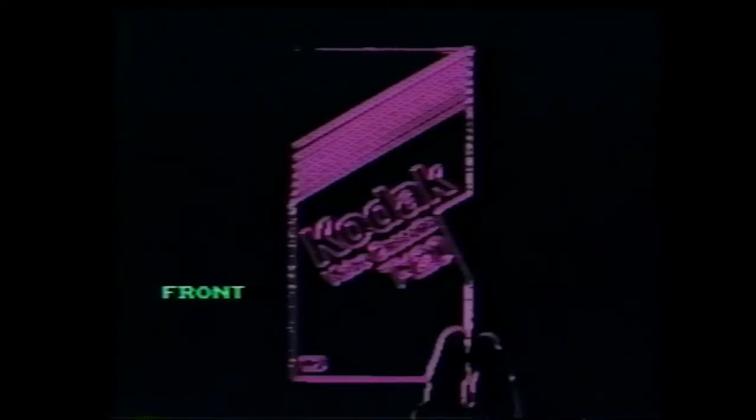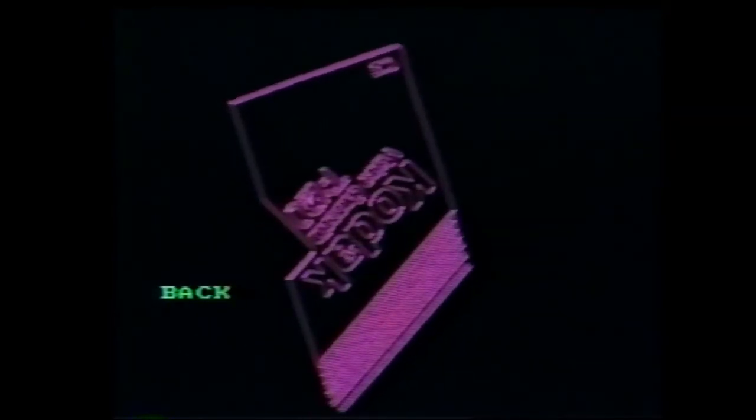Pattern matching algorithm running on Pipe and the 386 computer matches edge directions and allows translation, rotation, and scale invariant recognition. Here it has been trained to recognize the front and back of this video cassette. This has many applications in sorting and inspecting objects that are not well fixtured or are irregular.